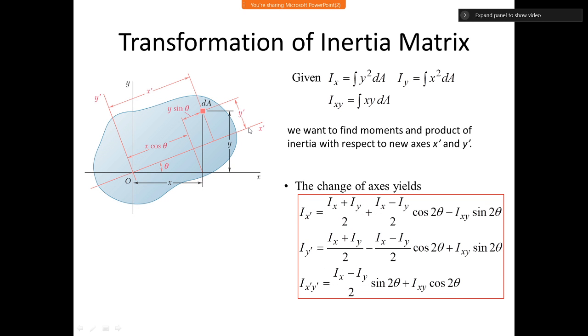So if your moment of inertia is high, your angular acceleration is going to be less. If your moment of inertia is low, then your angular acceleration is going to be high, for a given amount of moment. So we want to find some directions for which the body is easy to rotate. So now we are going to talk about objects which are not symmetrical, and three-dimensional objects.